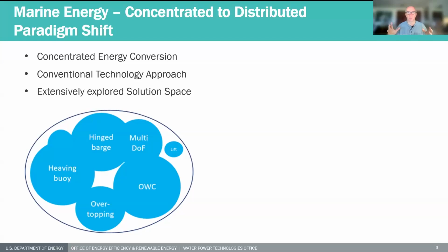So how do we bring the hydrodynamics together into a joint, a linear bearing, relative or absolute? How do we accumulate water flow in overtopping devices? How do we accumulate airflow in oscillating water columns to have it in a concentrated way to deal with that, and then apply power conversion mechanisms that we are familiar with, where we then maybe have challenges like bringing the velocities up to what a generator would like to see, but they're all in some way concentrated. Even lift-driven devices, a very different species, would try and get the hydrodynamics onto a shaft.